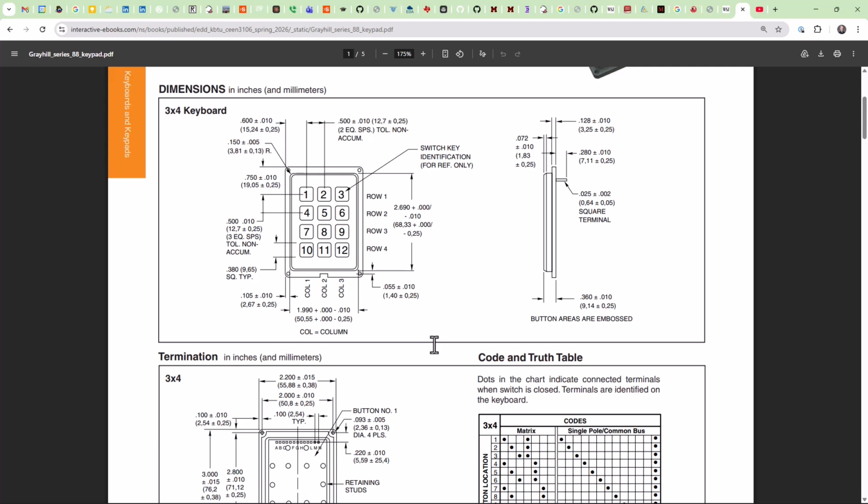So the basic idea is, we'll turn on one of the rows. Now, in our design, we're going to call this row 0, row 1, 2, and 3. We're always going to count from 0. We would put the value 1, a plus 5 volts, in row 0, and we would put zeros on all the other rows. This guarantees that all these rows have a defined voltage applied to them, and of course we do that quite simply using a decoder.